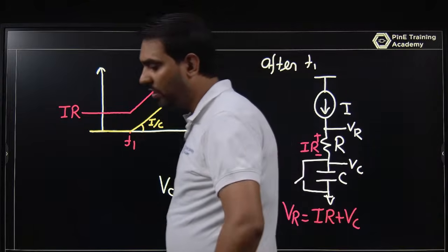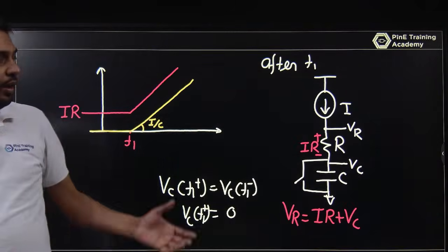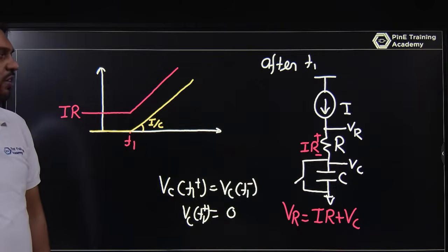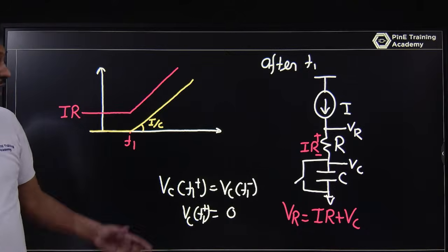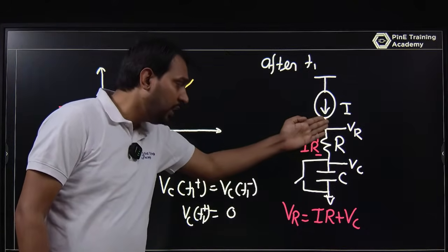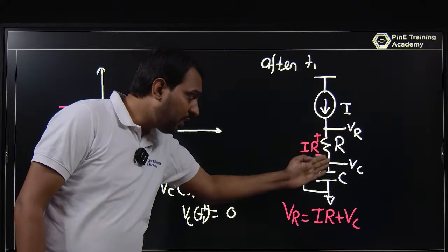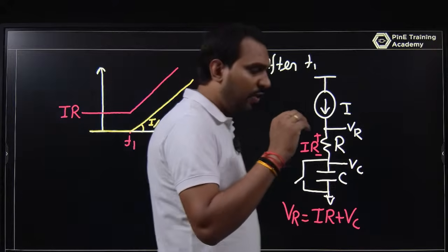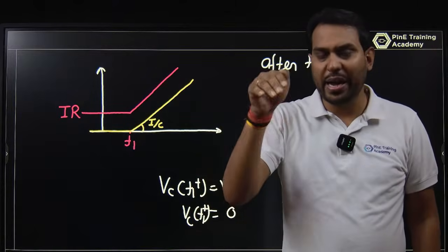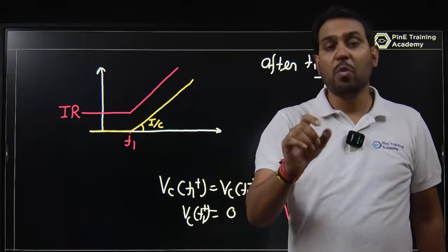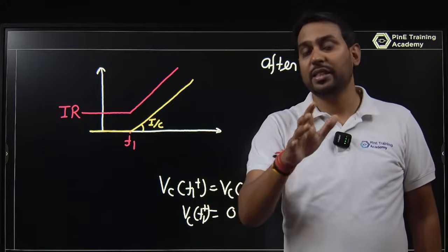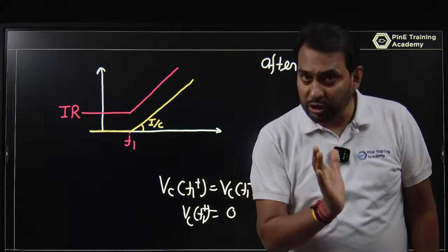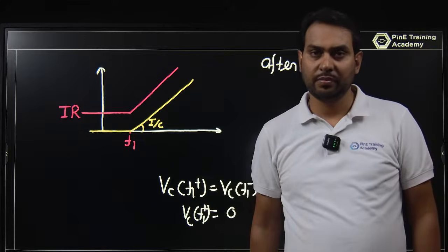Okay, so once you go for the interview, they will try to ask in a way, okay, you have a current source, you have a resistor, and you have a capacitor. What is the resistance? What is the voltage at that node, and what is the voltage at C? And if you are thinking in a way, whenever a current is entering a capacitor, it is always from one constant slope, that is I by C integration of dt. So voltage will go in a ramp function.